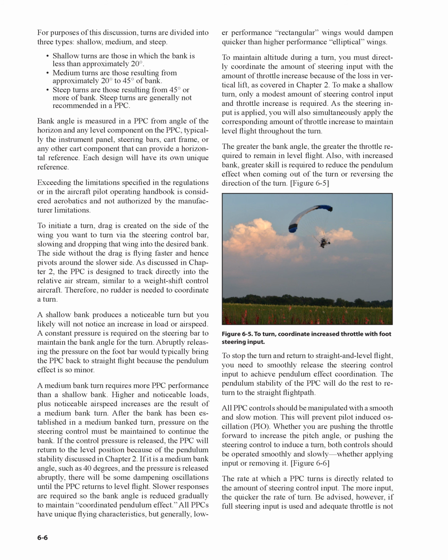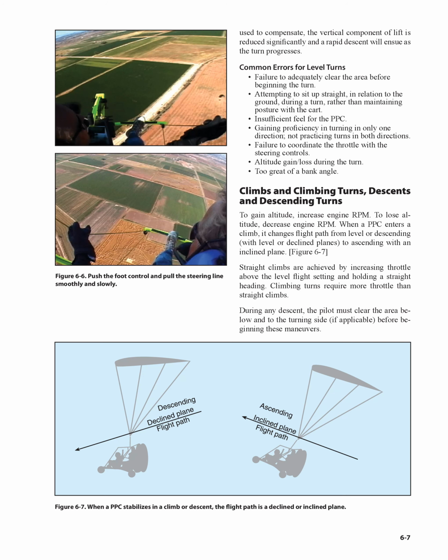Whether you are pushing the throttle forward to increase the pitch angle, or pushing the steering control to induce a turn, both controls should be operated smoothly and slowly, whether applying input or removing it. Figure 6.6, the rate at which a PPC turns is directly related to the amount of steering control input. The more input, the quicker the rate of turn. Be advised, however, if full steering input is used and adequate throttle is not used to compensate, the vertical component of lift is reduced significantly and a rapid descent will ensue as the turn progresses.